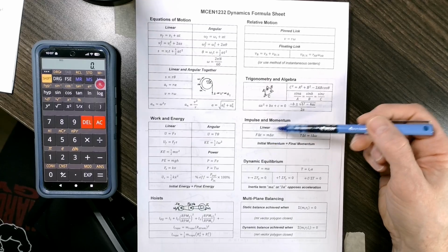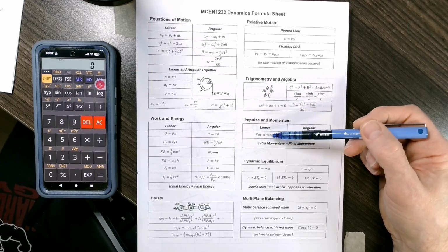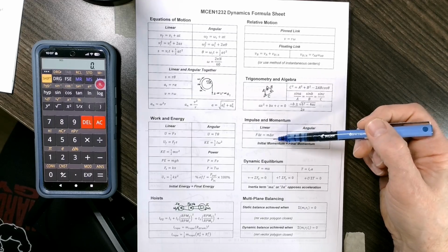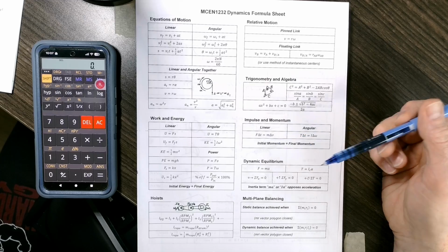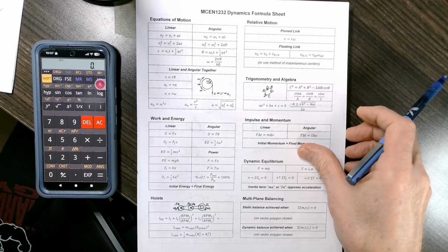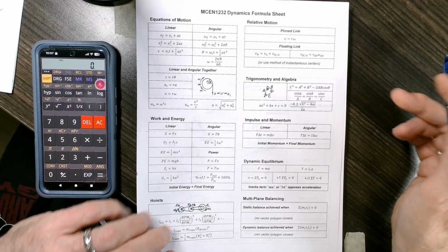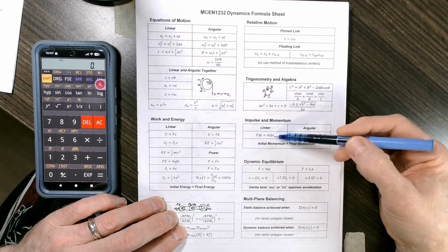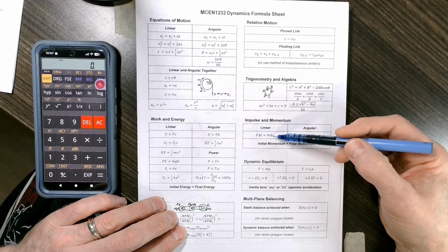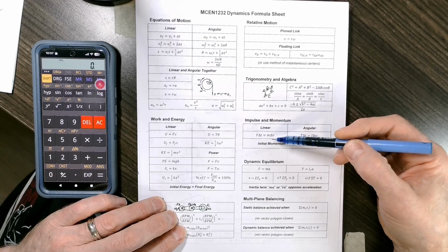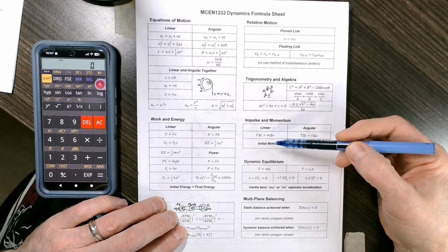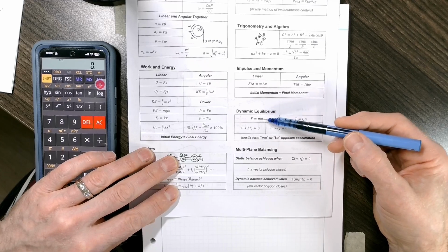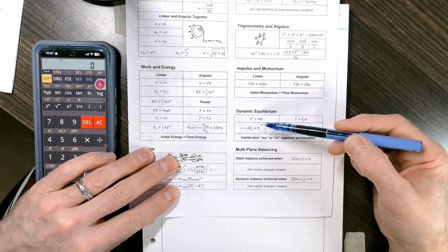So it's well suited to situations where you are interested in knowing the time or the velocity. But there are other measures of performance, and they are acceleration and displacement. This method doesn't address those directly. You can't get acceleration or displacement out of it. You can only get time or velocity. If you happen to have inputs that align more closely with the kinetic method called dynamic equilibrium, in which case you have acceleration, that may be a better fit.